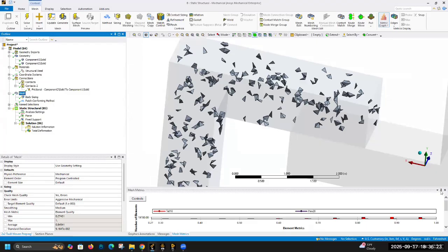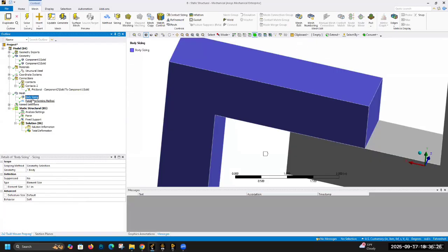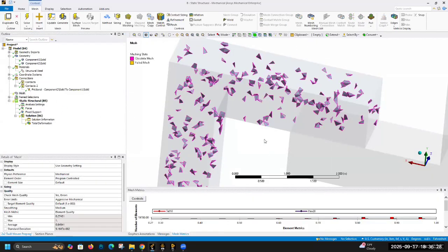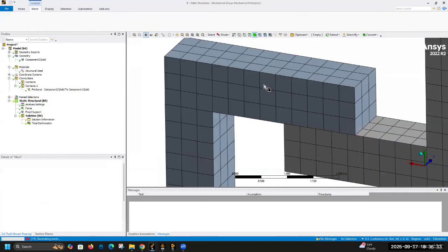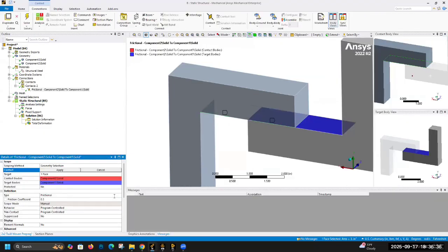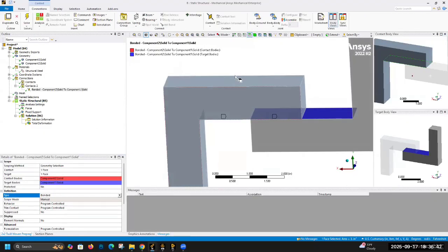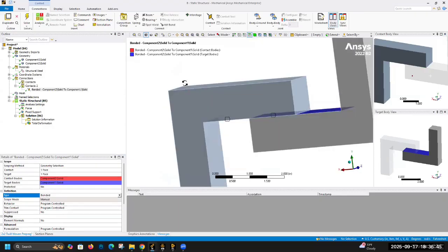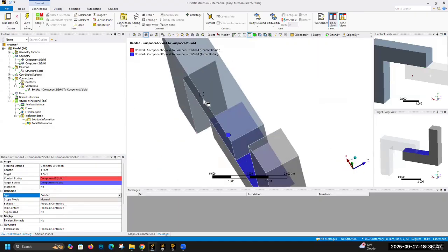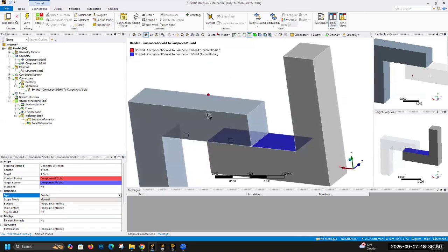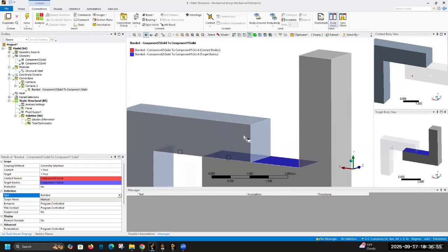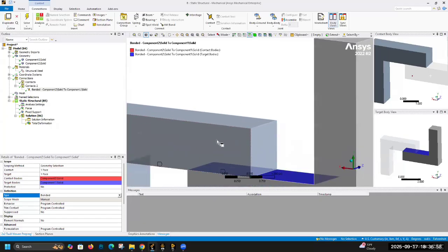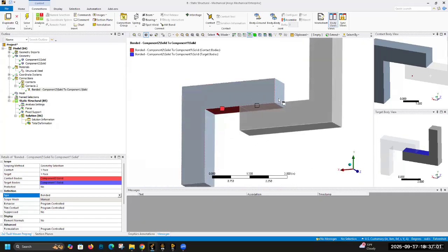Quick question. Yeah, what's up? When he first loaded this geometry into ANSYS, it predetermined a contact surface. What kind of contact surface did it predetermine? Like what was that friction setting? Yeah, the first setting that it automatically does is bonded. So it's always bonded? I can't guarantee it was bonded, but I think whenever you open it, it does automatically put it as bonded. I think the newer versions actually have some of that, but I'm not exactly sure. Most of the time when it gets defined, it looks at surfaces which are touching and says, okay, these are bonded. Great. Gotcha.